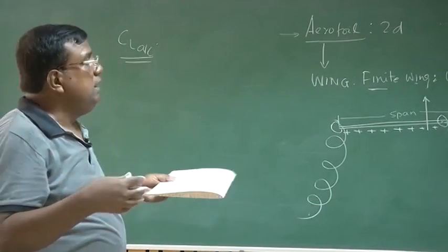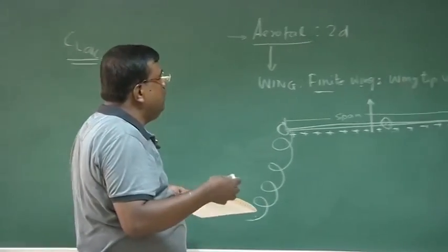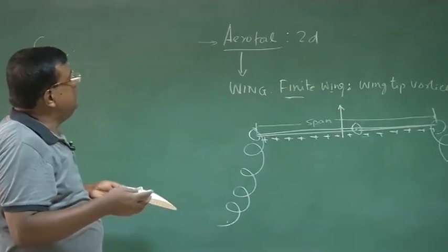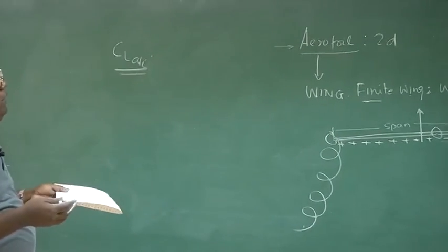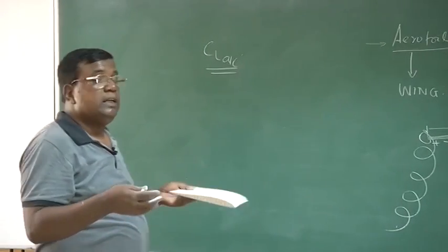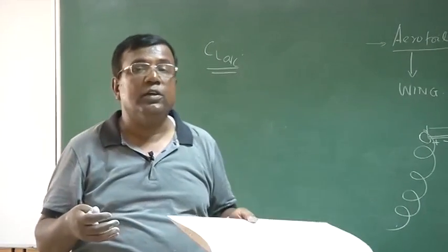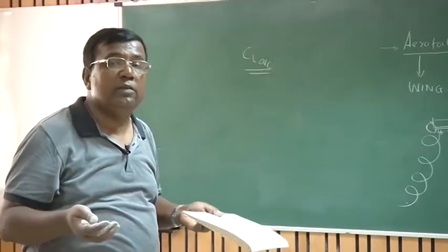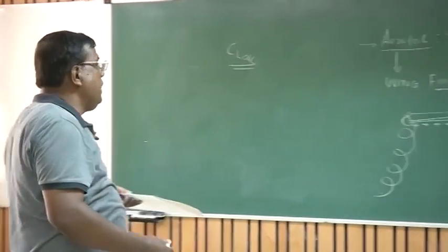So in the language of airplane aerodynamic modeling, we can always say that the lifting characteristic gets changed because of downwash, or the CL alpha may also change because of downwash.